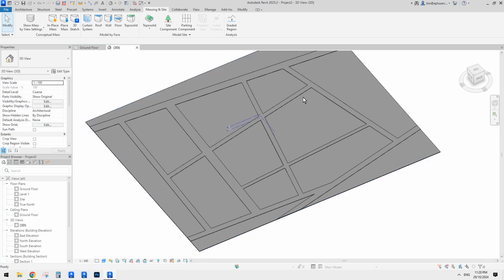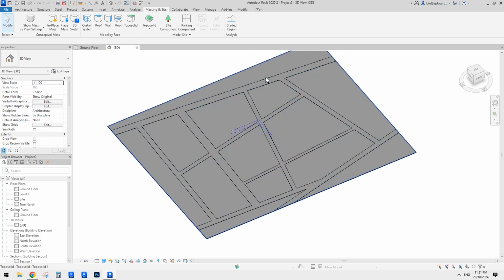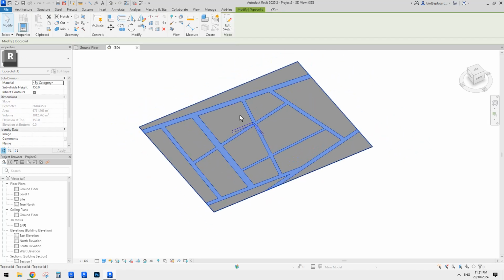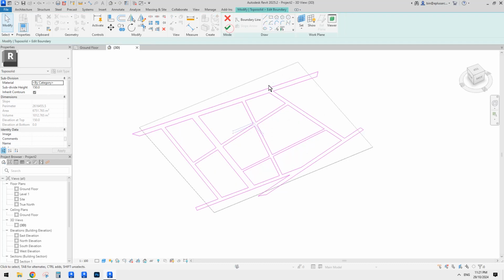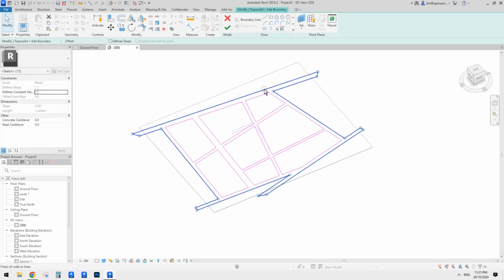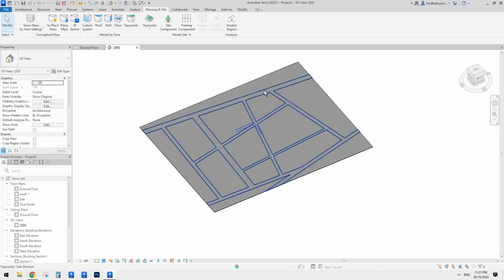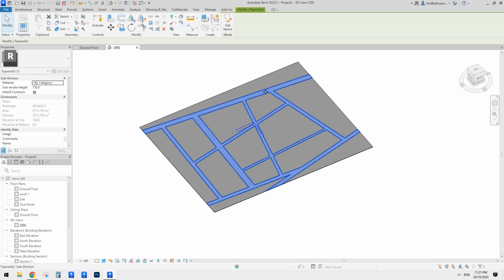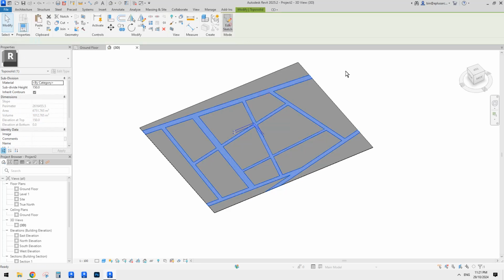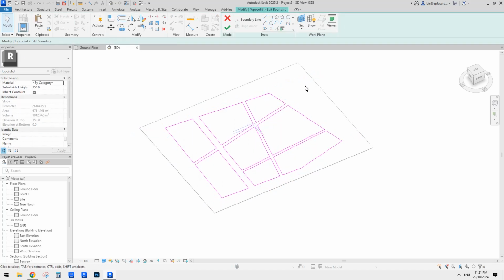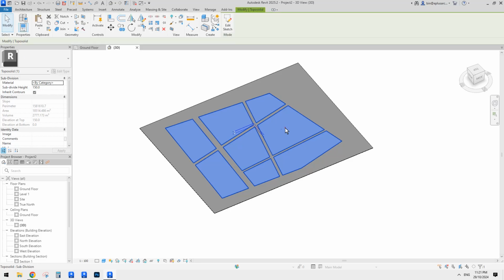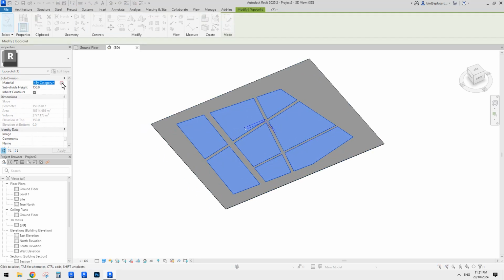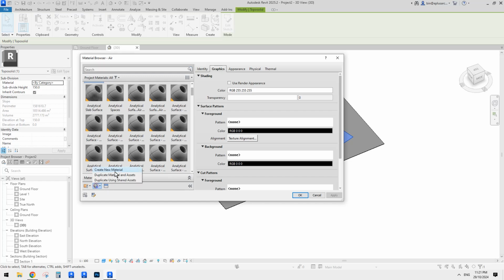What we can do is, because currently this one's a road, right? If we edit sketch and just delete... hang on, should we delete? Let me just do this. I'll copy, Control C first, and then I'll edit, tab, select, delete, finish. Now we have the site, right? So we have all the site, and for the site, maybe I'll give it a green color material.